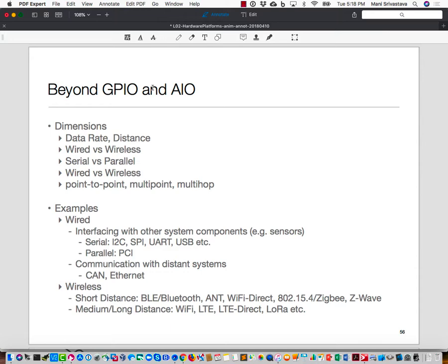So generally speaking, these are standards that have emerged for specific ways to talk to peripherals. And they've often been pushed by different companies and have become de facto standards. Also, in some cases, they may not be standards, but they're so widely used. PWM is a great example that oftentimes MCUs provide. I don't know about our specific MCU, but many MCUs have PWM hardware built in, and they will just let you write the duty cycle ratio, and it will take care of the rest.